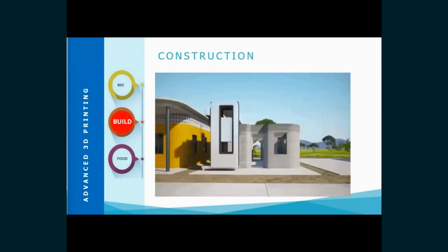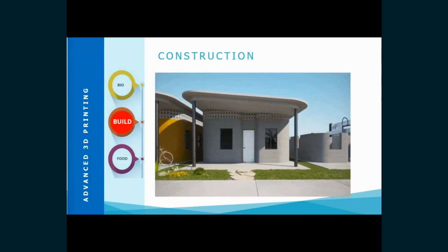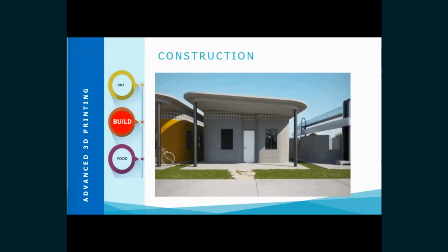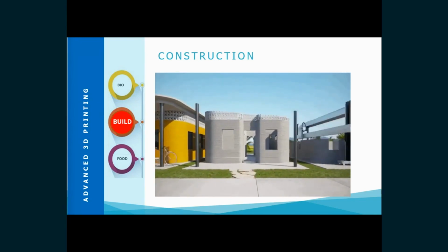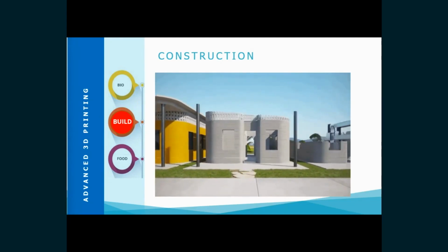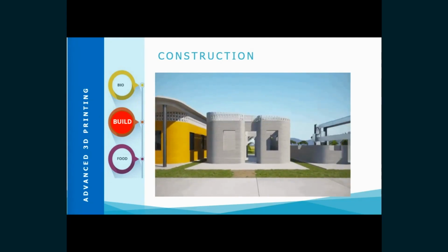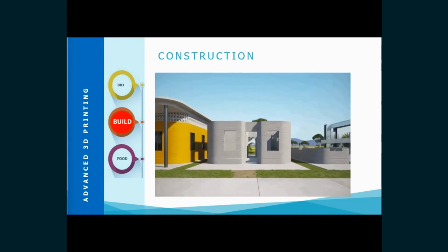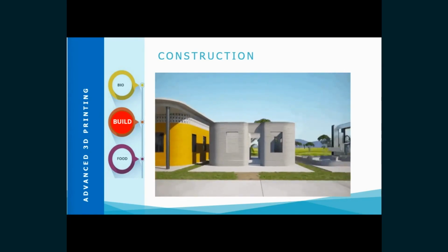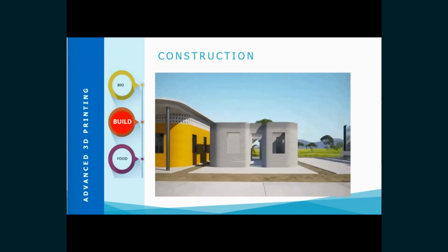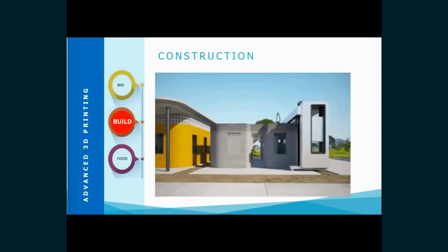Construction 3D printing is a rapidly growing area of material extrusion because it reduces the need for labor and cuts down construction waste. 3D construction printing technology is used today for building homes, architectural features, sculptures, bridges, etc. The technology involves using extremely large scale 3D printers to extrude a building material such as concrete, clay, etc. through an engineered nozzle head. These machines generally come either as gantry or robotic arm systems.